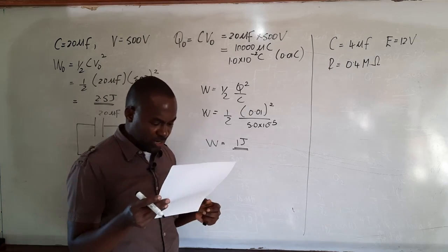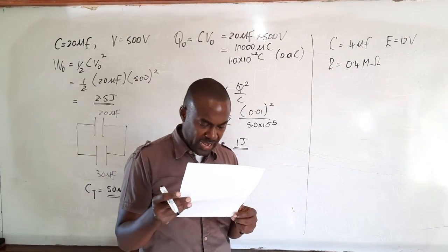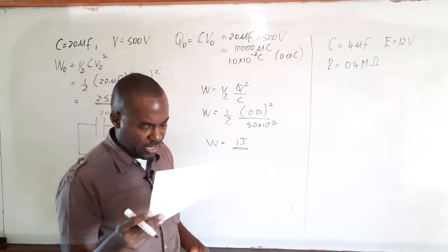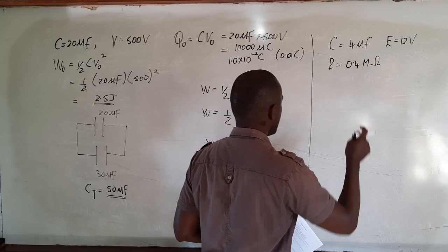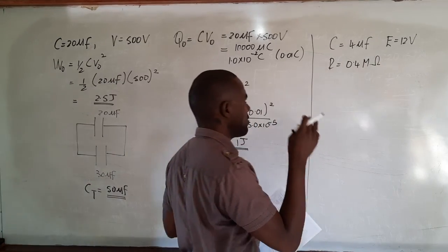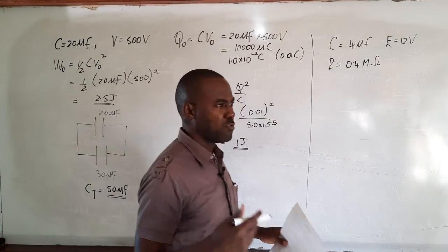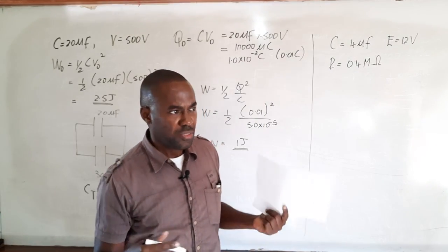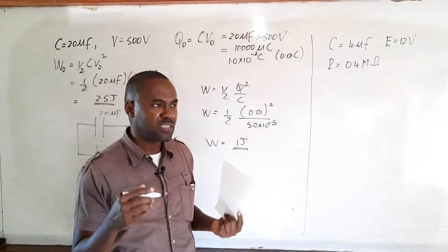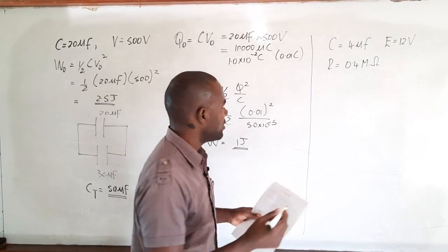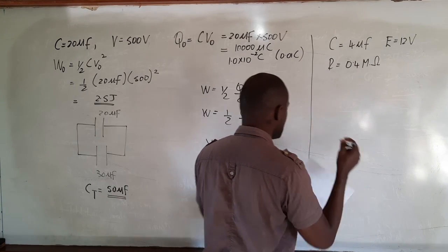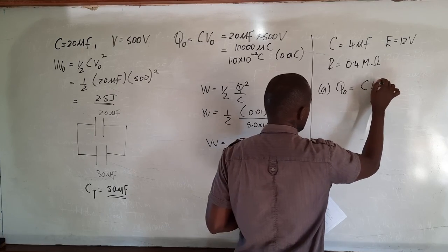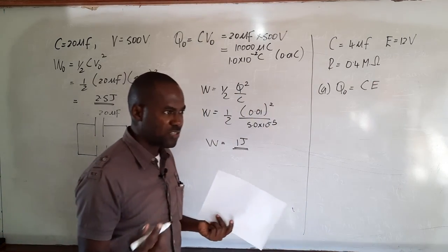Calculate the initial charge stored in the capacitor and the charge on and PD across the capacitor 2 seconds after it starts to discharge. So let's look at this. We have the battery EMF, which is 12 volts, and we have the capacitance of the capacitor. Now, generally, if a capacitor is charged by a particular battery, after it's fully charged, the PD across the plates of the capacitor will be approximately equal to the battery's EMF. So therefore, to find the initial charge stored in the capacitor, we can say that Q naught is equal to C E, where E, of course, is the battery's EMF, right?